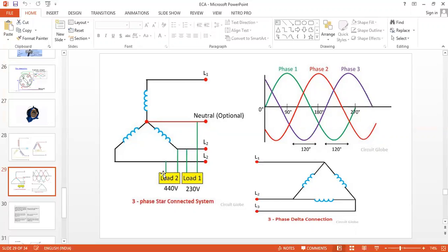You can see this green arrow mark, which indicates diagrammatically the voltage present between L2 and L3. The voltage present between any two lines is called line voltage. The voltage present between any line and the neutral is called phase voltage. So near the pole we have 3 wires followed by 1 neutral wire. These are power wires, not internet wires, so don't get confused. Power lines near your house will be 100% 3 wires and 1 extra 4th wire. Today only you can check.